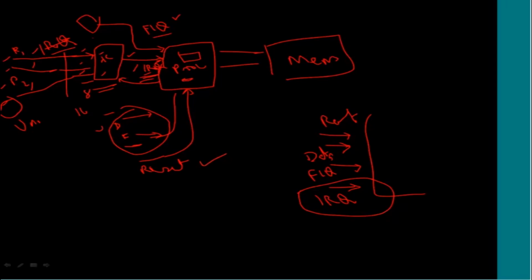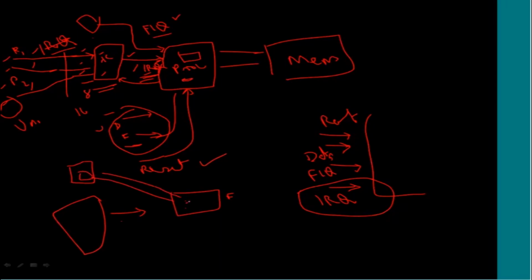Now when the IRQ handling happens, when this interrupt happens, the processor may not know which device has interrupted if it is coming through a controller. So what will it do? At the first level, it will try to find out which device is interrupting, and then it will read that device. Suppose some data is waiting, it will read it from there and keep it in memory, and then defer the processing to the second level.